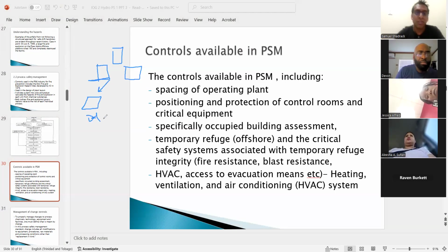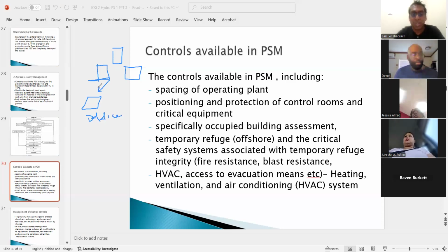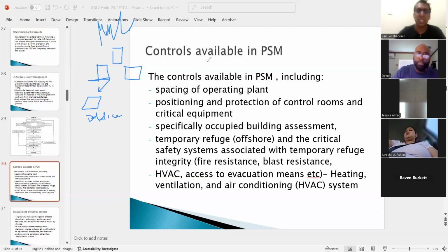In the event of a fire or an explosion, all of the things like wind direction would have been considered to put the office in a way that if there was a fire here, the blast zones and stuff, the office wouldn't be in that pathway, right? So that's the purpose of compartmentation. That's the purpose of getting the risk estimate for each area. It's to suggest a control, right?